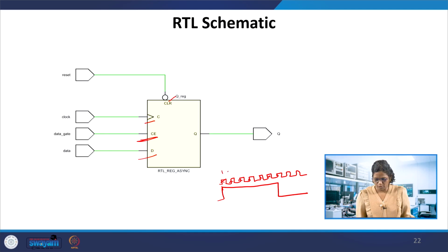So if you want to restrict this clock period, suppose up to these 1 2 3 4 5 6 7 clock edges, I want this clock to be used for the data, and after that it should be 0. The data need not be operated, or need not be assigned to Q. So using this clock, we form a gated clock that is available for a certain period of time. That means this clock is gated up to 1. There is logic to develop this gated clock as well.